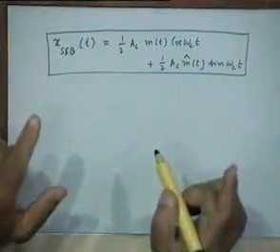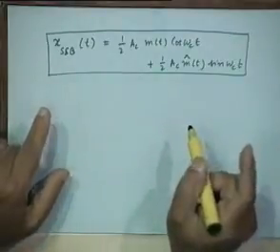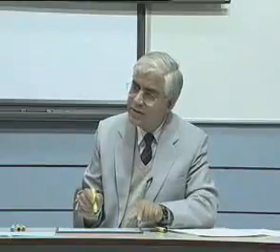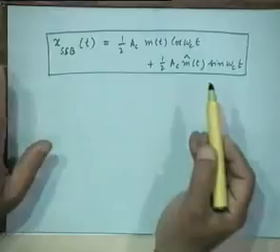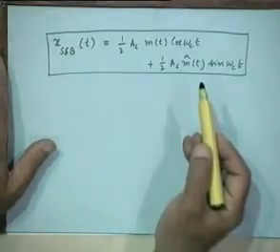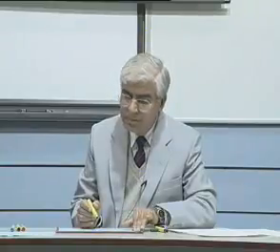Any questions? I hope you have followed the derivation. It is fairly straightforward. Basically it makes use of the properties of the Fourier transform and the properties of the Hilbert transform, right? And what kind of SSB signal is it? It is a lower sideband signal, right? Now it's a very simple exercise for you to go through the whole process again and show that if instead of plus here I have minus here, you will get the upper sideband signal. Okay, it's a very interesting and useful mathematical closed form expression for the SSB waveform.